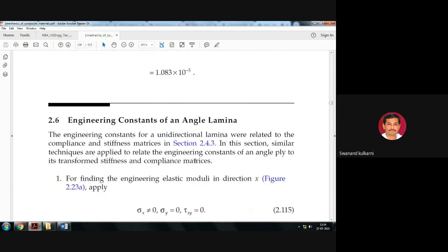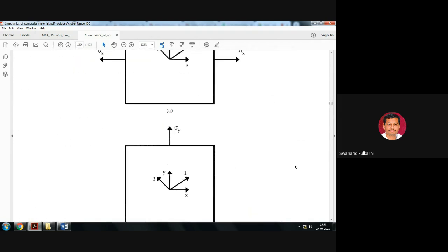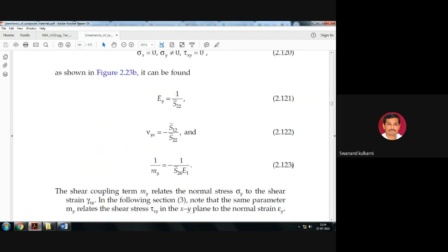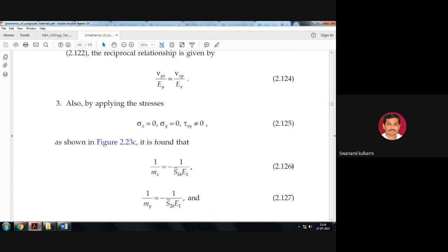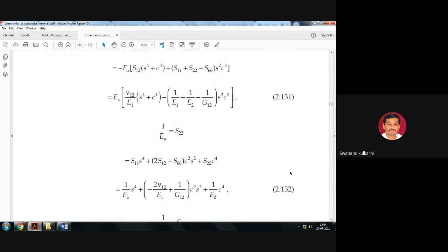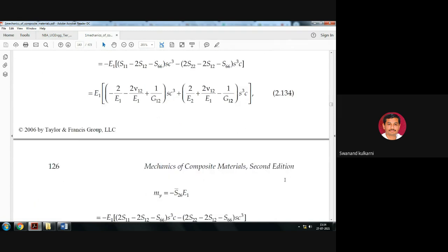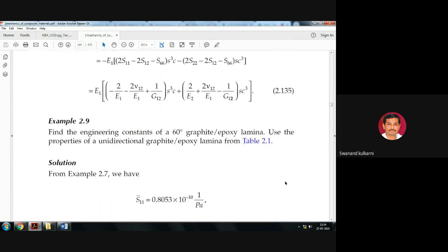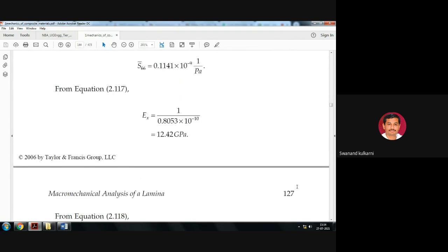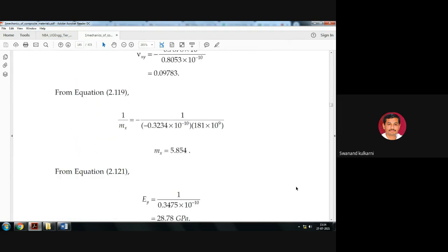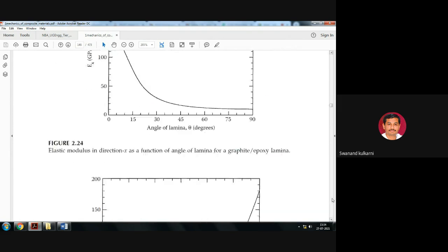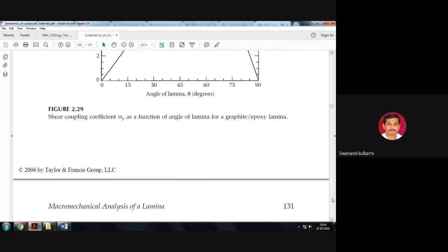So now, in the example we are observing, we have to use the maximum stress theory in order to identify the safe limit of the stress, and based on that safe limit of stress we can go for analysis of the maximum load that can be applied, and identify the maximum value of load that can be given here. Is it okay?